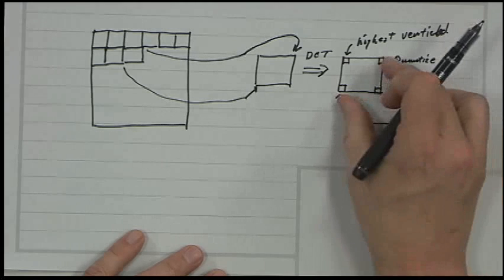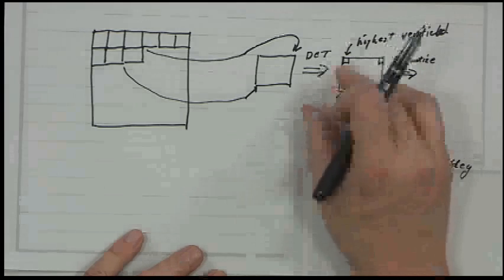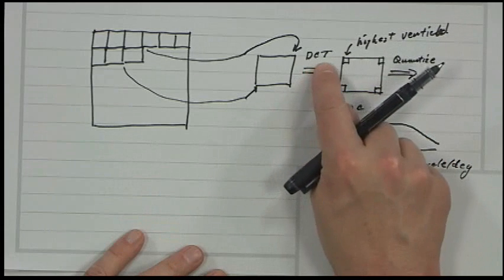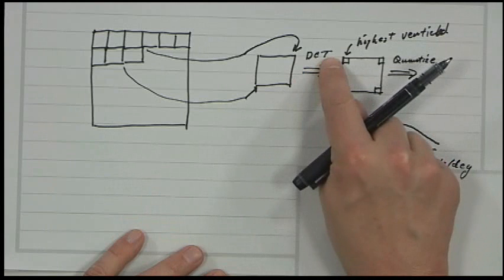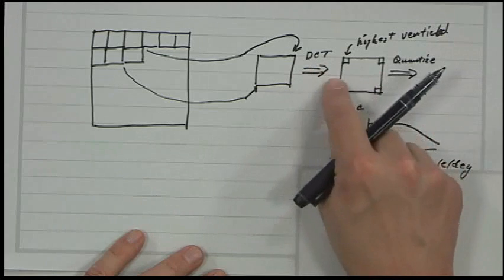The DCT, if properly normalized, is an orthonormal transform. Using conventional normalization, it's not orthonormal. It's just orthogonal, but not normal. But it's easy to adjust for that. You just divide by some appropriate constant. I think it's something like the square root of n.